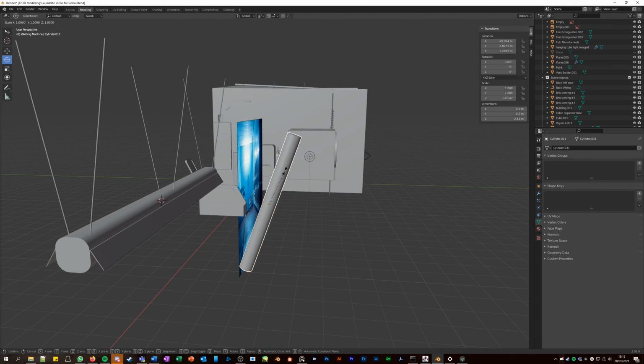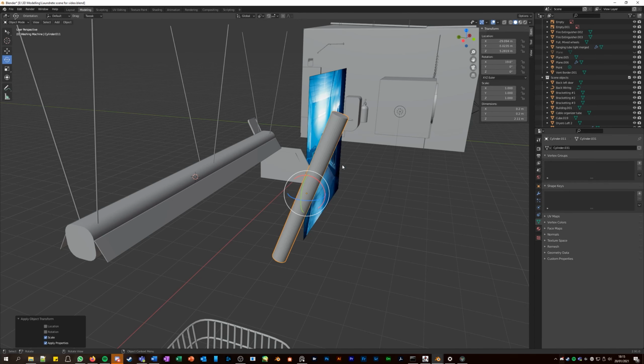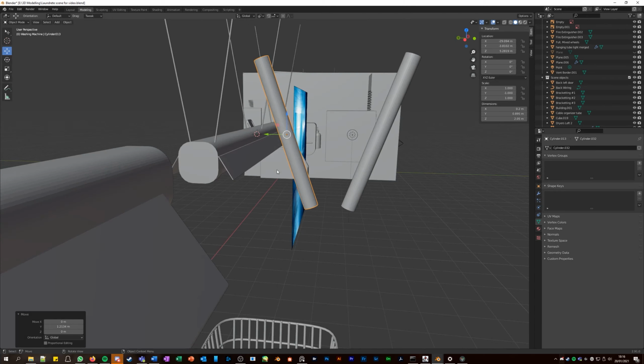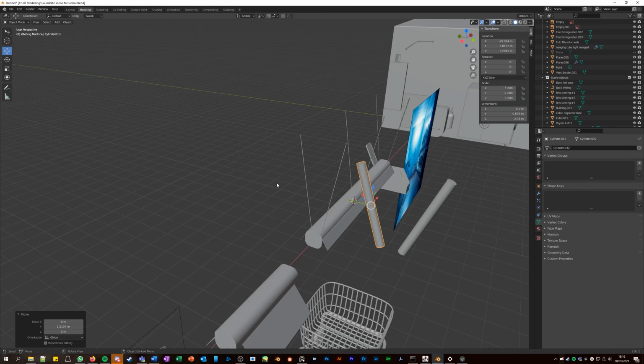And then I actually took it, duplicated it, and scaled it. As you can see, I've got a scale, but then I did it on the y-axis to the -1, reset the scale and rotation, duplicate it, and then scale along the y-axis. As you can see, it's now locked on the y-axis to the -1, and that flips it to the perfect angle, same angle, but on the other side. That's what I did for all of them, duplicated them down.